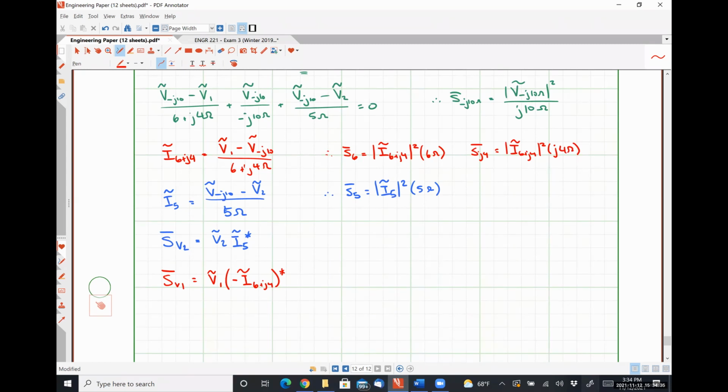I don't know that it matters, actually. What the negative sign is going to do is change the sign on the real part and the imaginary part, and then you just change the sign back on the imaginary part from the conjugate operation. So I don't think it would actually matter if you conjugated it first and then made it negative. If you calculate it without the negative, you just have power supplied. Yeah. Thank you very much. Yeah, so that's problem 1 in, I don't know, 4 or 5 minutes. Obviously, we didn't do any of the actual math involved, but the circuit theory is all there.